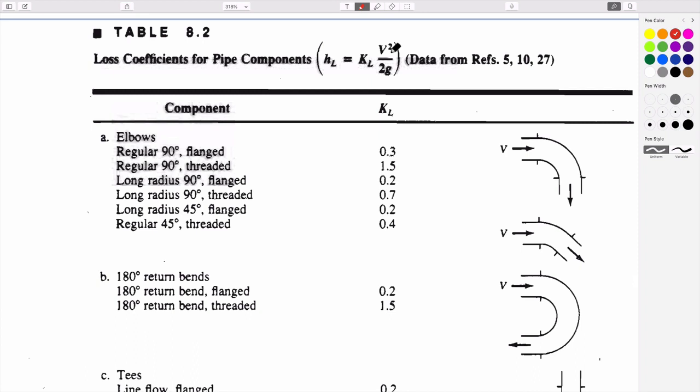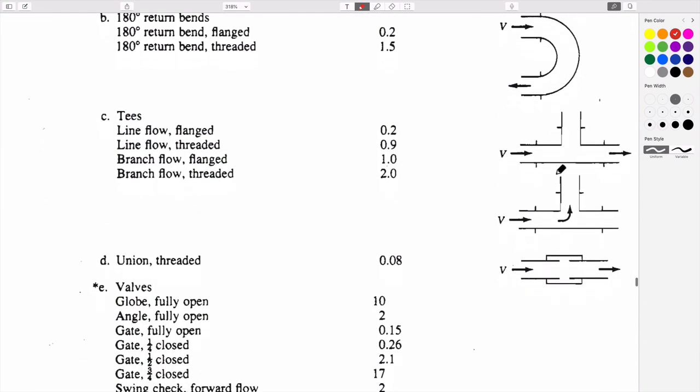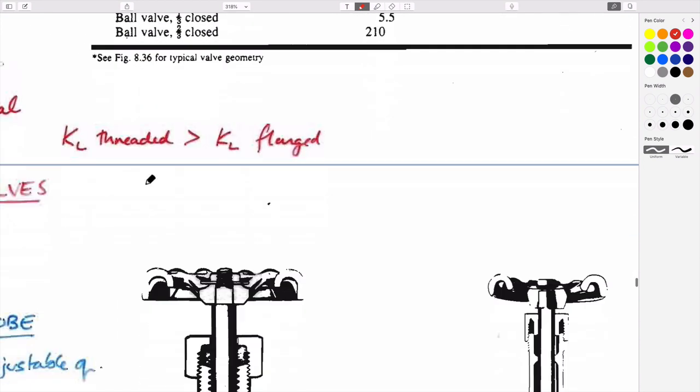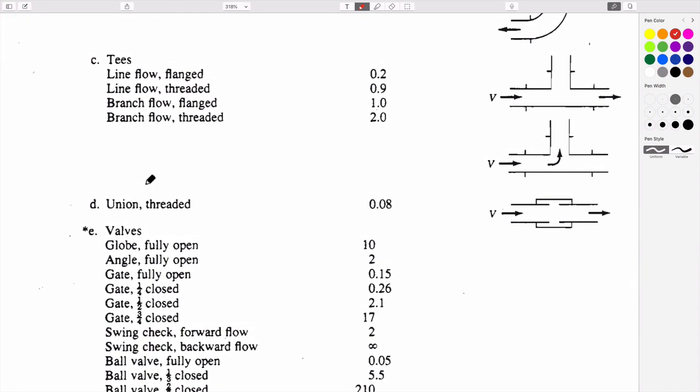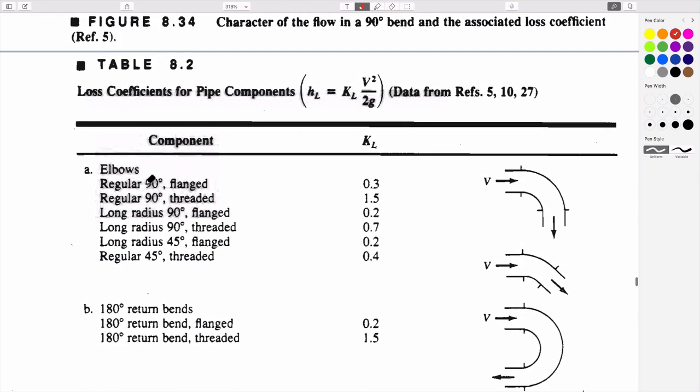And implicit in this, as we mentioned last time, is that we're basically assuming that the behavior within these fittings, whether it's a bend or a junction or individual valves, which might look like this, if it flows through this, is that the flow within these is turbulent. The reason that we can suppose that is that we have a single constant magnitude of this typically, which doesn't vary with Reynolds number. And so in terms of where we are on the Moody chart, it's a location where the Moody chart lines are horizontal, not the ones on the left-hand side.